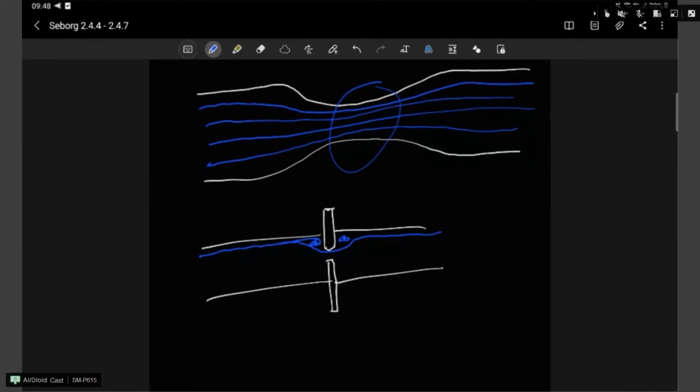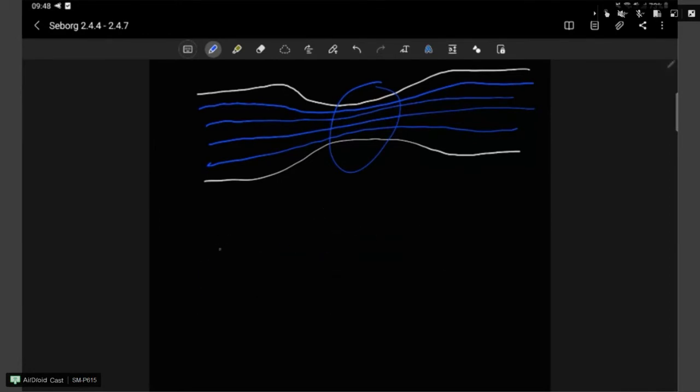But for simplicity's sake, obviously, we assume that the orifice plate behaves in such a manner that we can apply the Bernoulli equation. In the case of a valve, because the geometry is a lot different, and in most instances your valve body would look something like this, where this would be a separation between the inlet and outlet. Not perfectly drawn to scale, but regardless.